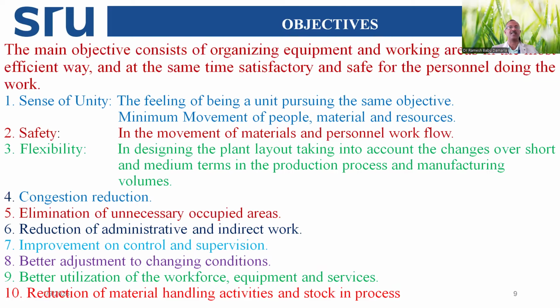Another objective is flexibility. So in designing the plant layout, take into account the changes of short and medium terms in the production process of the manufacturing plant. Whether the existing layout is flexible for change or the new layout being planned is flexible for future changes must be kept in mind, because technology is changing, customer wants and needs will change. So we should keep this in mind while designing the layout.